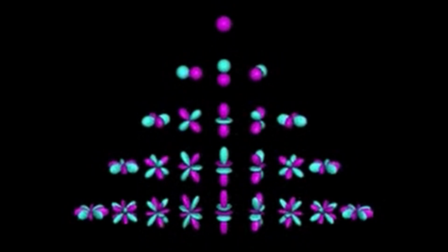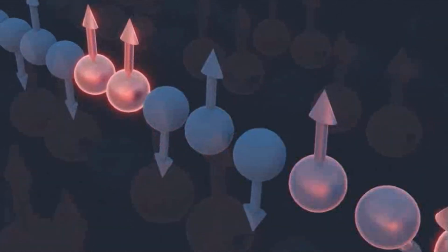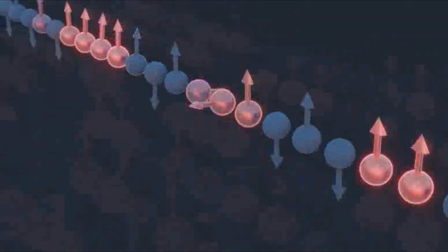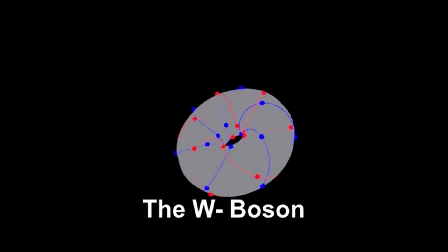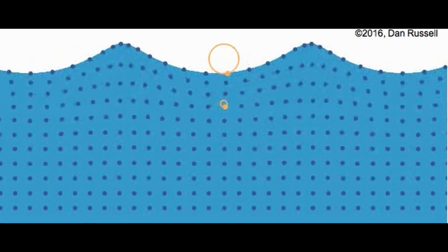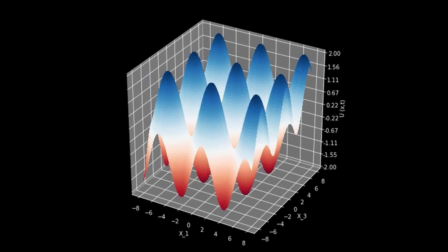3. Energy quantization. The energy required to add an electron to the island is given by E_c = e²/2C, where e is the electron charge and C is the capacitance of the island. If the thermal energy, kT, where k is the Boltzmann constant and T is the temperature, is much less than E_c, the Coulomb blockade effect becomes significant.